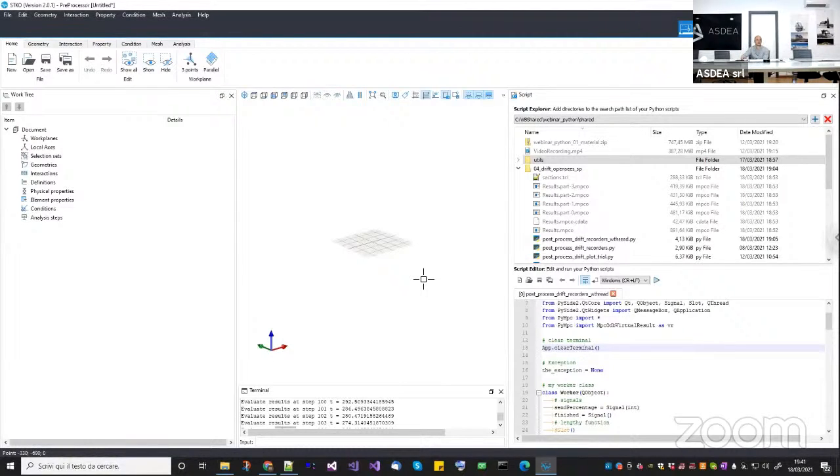Can we run STKO from this API from an external file? Actually, you can. You need to link to a library which is inside STKO, but some of the things that are there will not work because STKO needs the application. So you can get just some subset of all the Python API that we have inside the PyMPC library. The problem is that you need STKO.